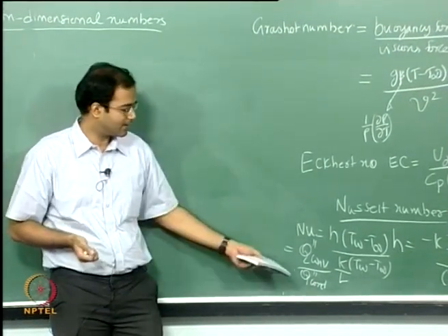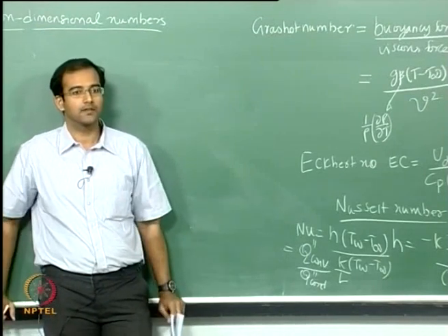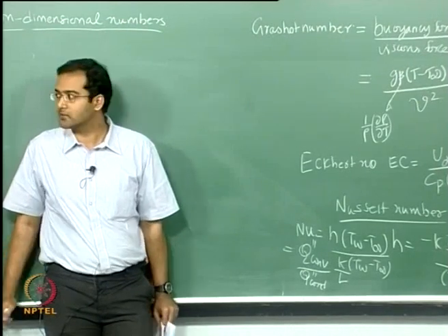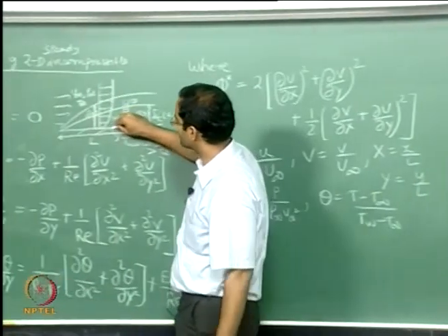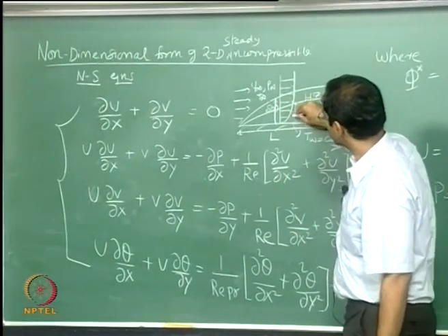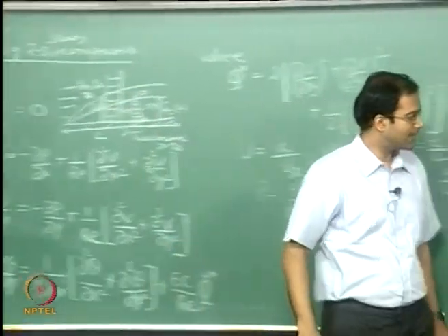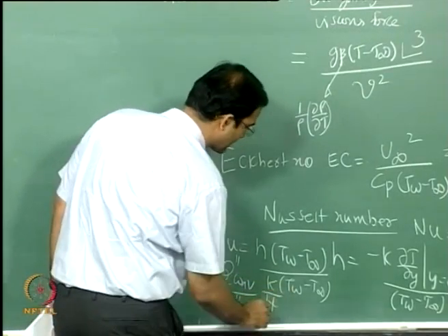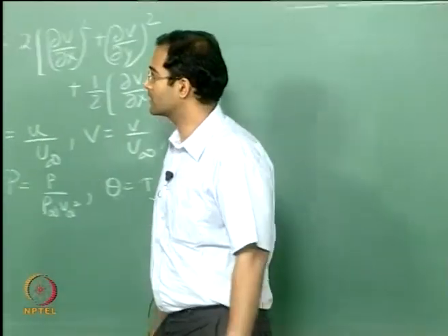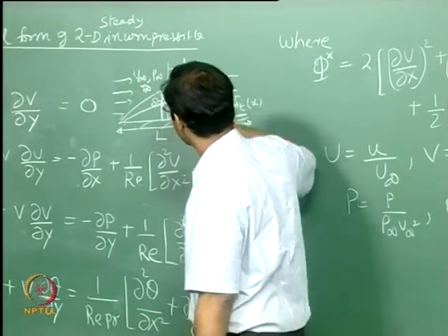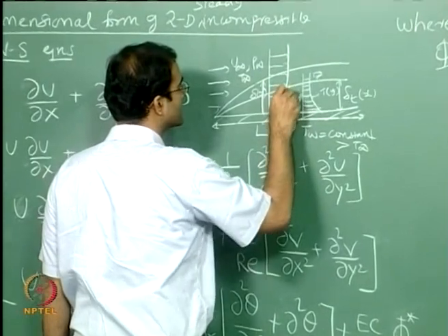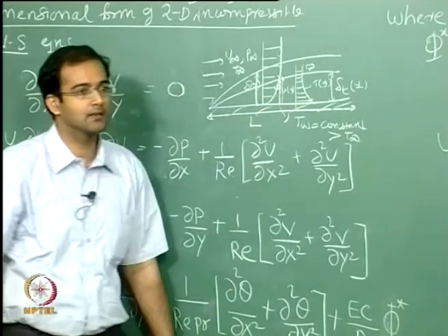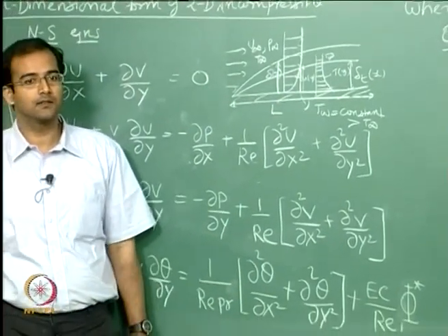If this number is equal to 1, then there is no contribution of advection. The heat is transported from the wall to some distance, let me use H instead of L here, to give you a physical representation of this non-dimensional number. It tells you, for a fluid element at a vertical distance H from the flat plate, the contribution of both advection and conduction over conduction.